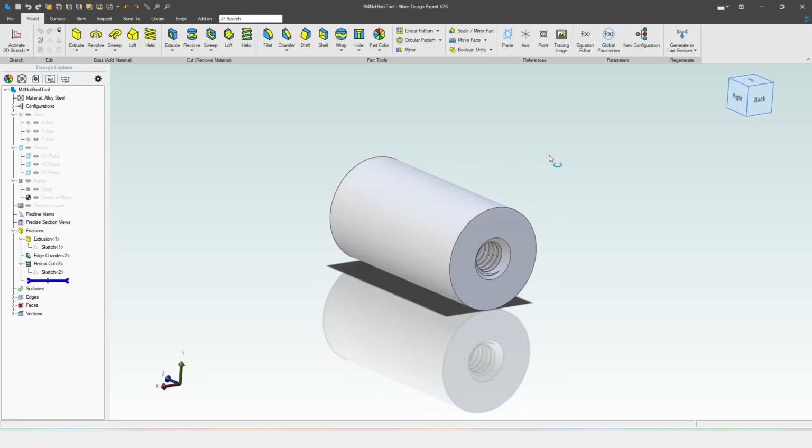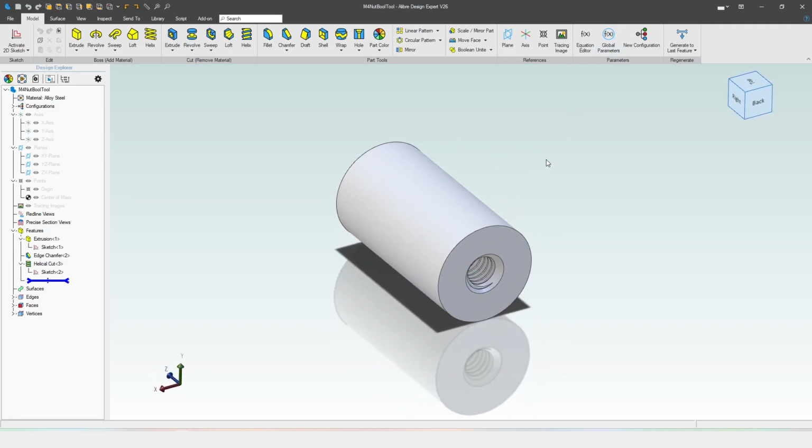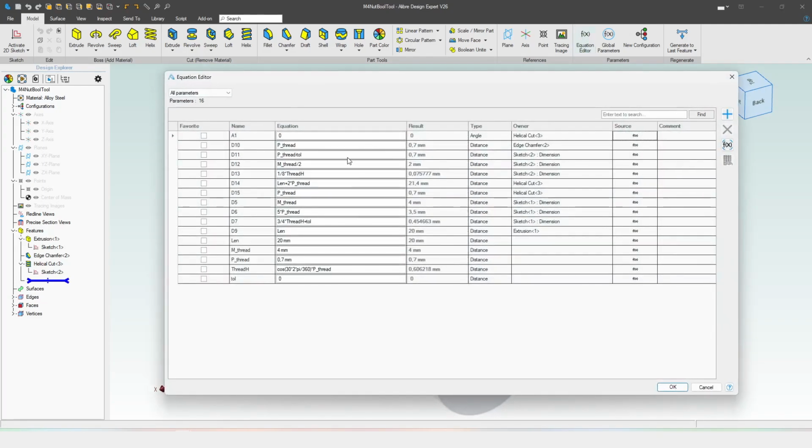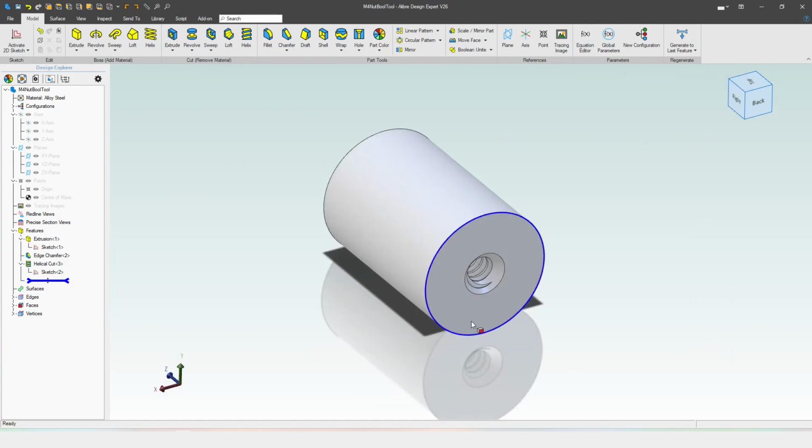So what the design library does is it creates an instance, and then as you save it, it crystallizes the equations. Okay, here's the 4 that we selected through our nominal thread drop-down menu. The nominal thread variable is not here, as you can clearly see. Okay, let's do something stupid and let's change the thread to 1 millimeter. Okay, also you can change the tolerance. Okay, so if we hit OK, you see that this thing changed dramatically.